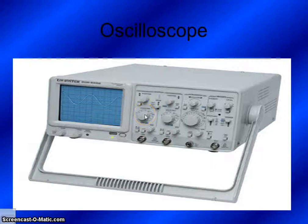Anyway, this one here is going to be determining your voltage. For the first channel, that's voltage, and this is voltage for the second channel. And this one is going to be the time, and the time has to be the same for both. Over here for voltage, you will have various units, but one of them is a volt. What this one does is the vertical positioning, and this little knob has a little marking on it, and it'll show you how many volts.